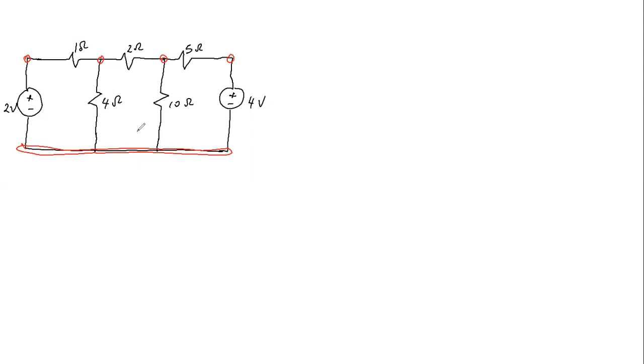As my own rule of thumb, just check for the essential node that is connected to a voltage source in the circuit. And this makes the perfect choice for us. This is also an essential node. So we assign a reference voltage of 0 volts. So at this point, the circuit is connected to ground.